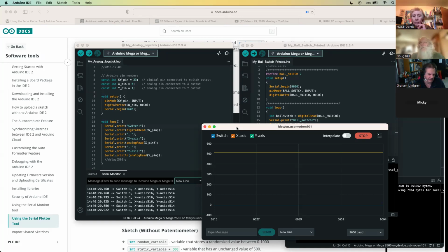It could be limited by the clock rate of the microprocessor then. It could even be that, depending upon how they implemented serial, high baud rates are deviated from the standard actual rate because of the base clock rate of however they're implementing that baud rate. In fact, it might even be that the baud rate doesn't mean much when you're not going off chip. I don't know.